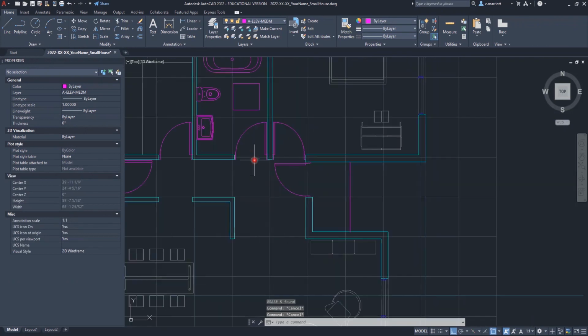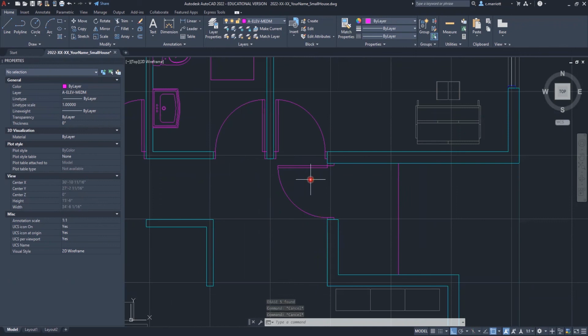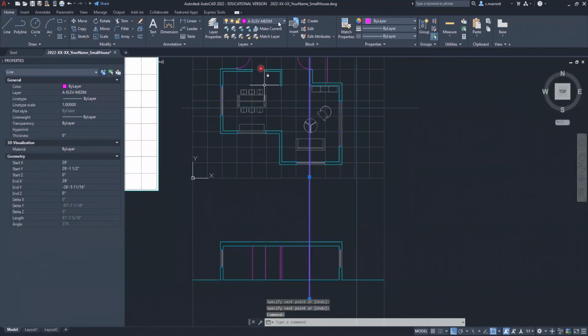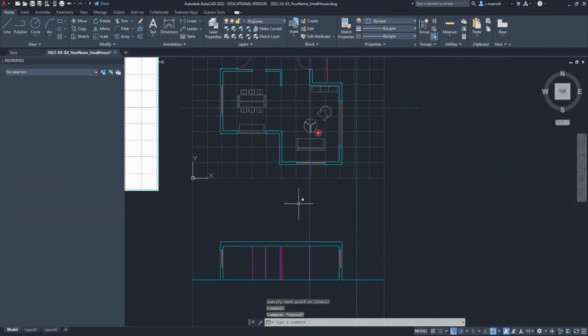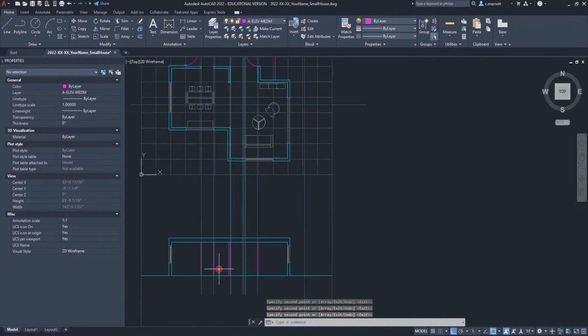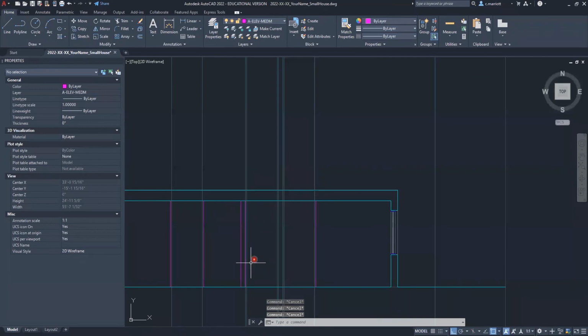Okay, and then the last set of lines would be all of these doors that are in the distance. So for these, I'm going to go ahead and create projection lines. I'm going to bring them down. Let's change my layer to projection. And then I'll copy each of these. And every single one of them here. And this frame is also going to show. Okay. My door height, remember from the front, the south elevation will be 84.